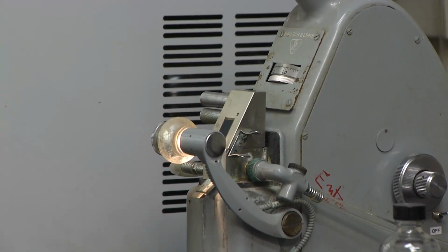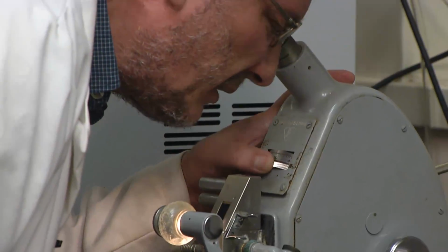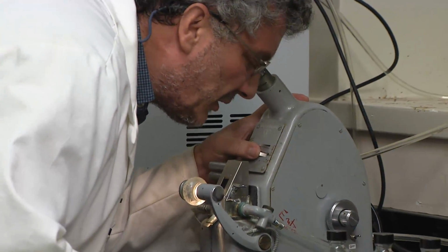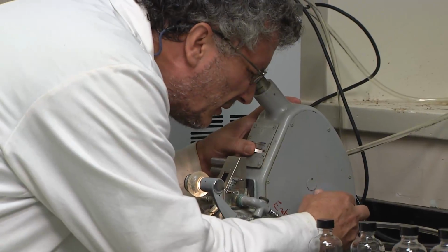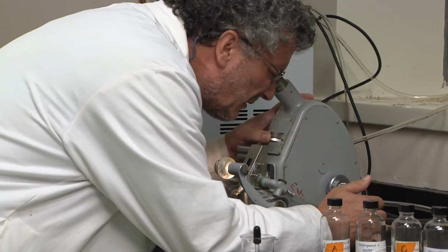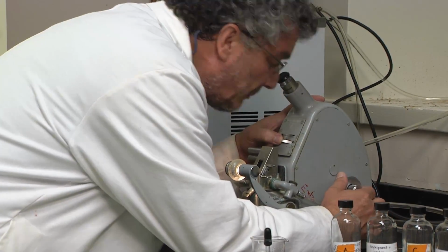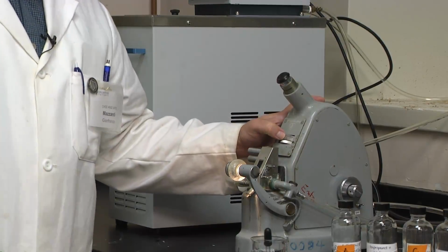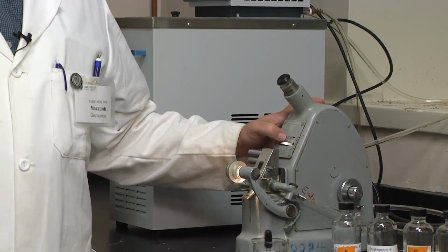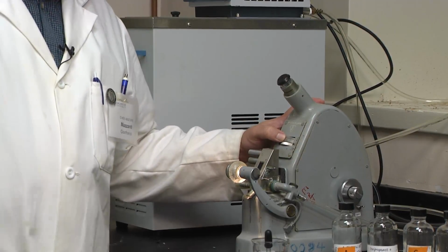So the light goes into that little window, and then I can first adjust it to find a sharp edge. And once we find that sharp edge, oh, this has moved too much. I need to find it there. Now we can create a very sharp edge. There, I find it, and that sharp edge will approximately tell you the temperature of the prisms, roughly. So now it's close to 18 degrees, although here the room certainly feels much warmer today.